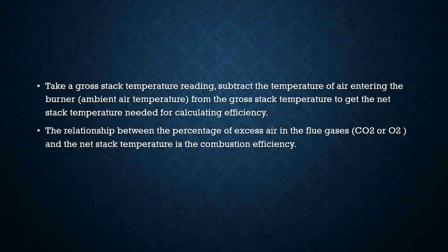Taking a gross stack temperature reading, you're going to subtract the temperature of the air entering the burner, which is your ambient temperature, from the gross stack temperature to get the net stack temperature needed to calculate your efficiency. Again, that is really, really important when you are doing these readings.